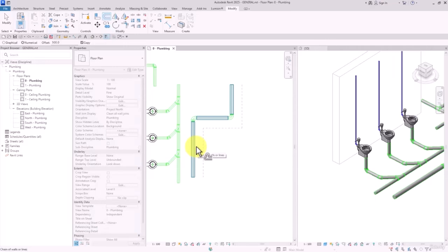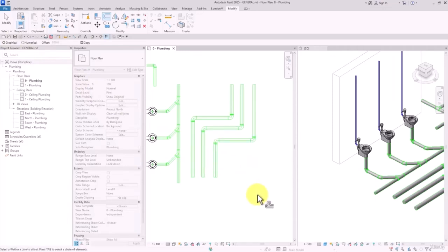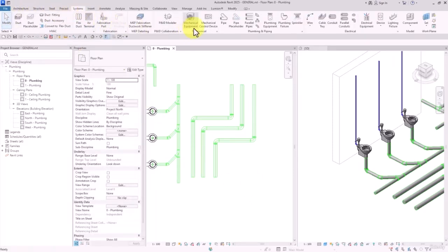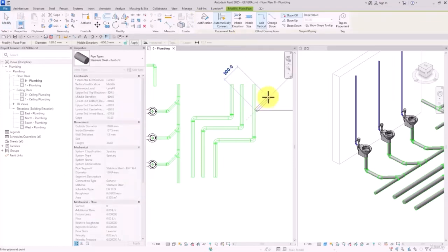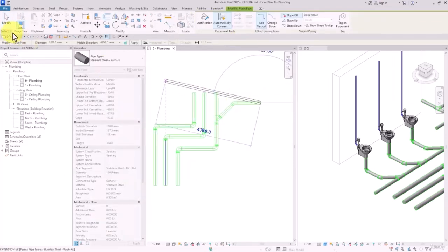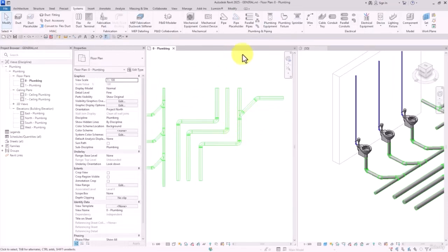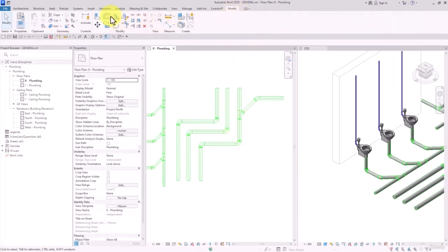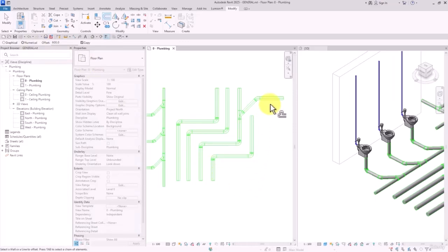Now, graphical, I'm going to select this. This would be our starting point and the ending point here. Now, let's say along this path, we have some sort of a junction. A junction, or you can call it a branch like this. Now, if I select the offset again, the path would be included all the way to the junction. And if we wanted to add the junction to our offset, we should do it separately like this. Then if we use trim here, automatically this fitting would be created. All right, let's move on.